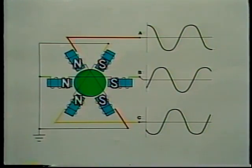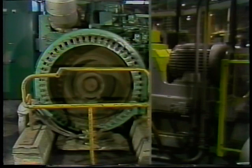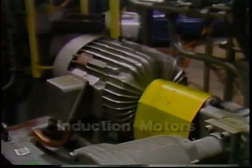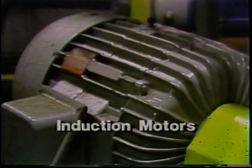Since there are 3 phases and they all reverse twice in each AC cycle, the stator poles in the 3-phase motor rotate at the synchronous speed of the motor. Now there are 2 basic types of single-phase and 3-phase AC motors: induction motors and synchronous motors. They differ in the way the rotor poles are produced. In induction motors, the rotor poles are the result of currents induced in rotor conductors.